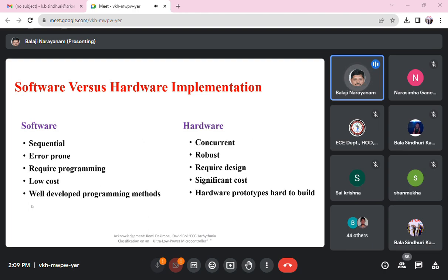But when it comes to the hardware, you require design aspects. Like you need to design a data acquisition system, or you should use the processor for converting the analog signal into a digital signal. An A to D converter needs to be implemented, and for example, you need a VLSI architecture for denoising of your biomedical signal, all that. So you require design skills if you want to implement it on the hardware.